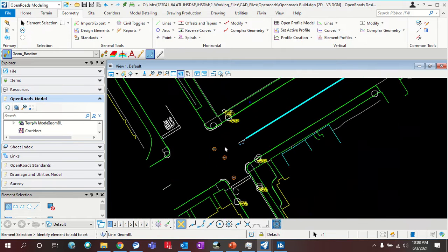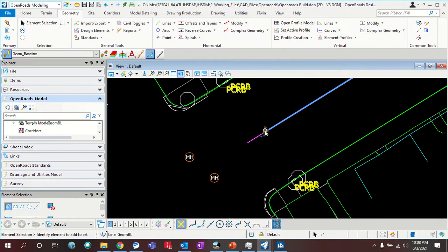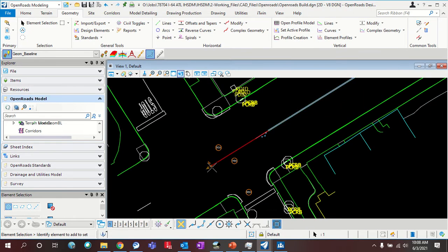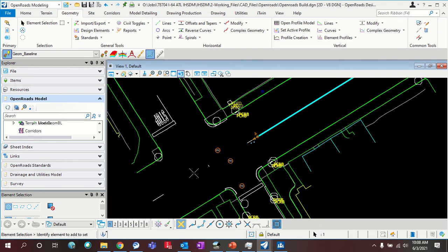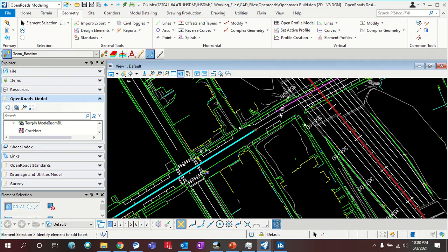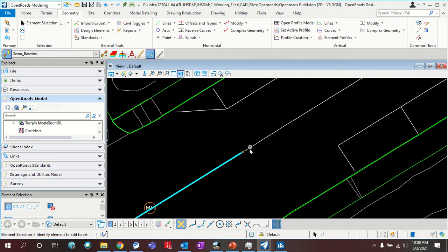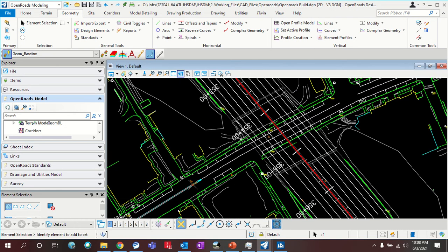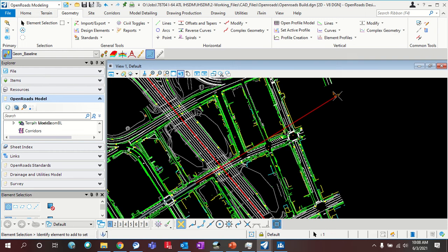first line. So for IHSDM, we typically tend to extend these into the intersection right at the center point. You would take it to the intersecting cross street or drag it through depending on what kind of analysis you're doing, but for now I'm just going to drop it in the intersection. This other point, we can snap that point and extend it way out because it's going to be cut when we add in an arc.